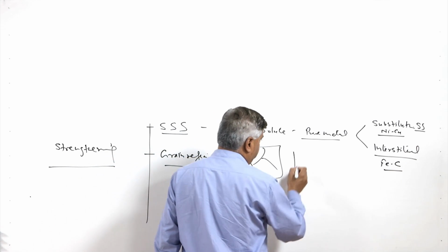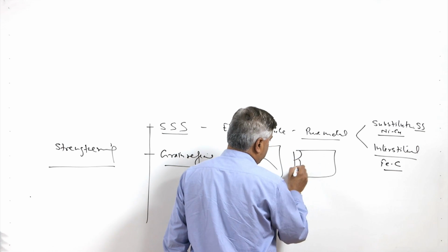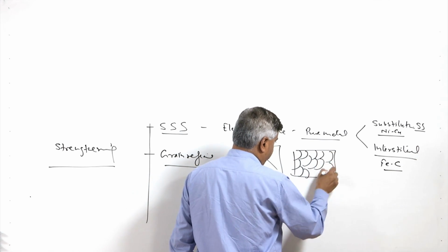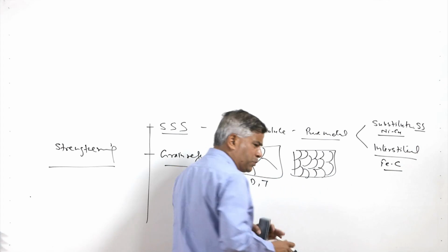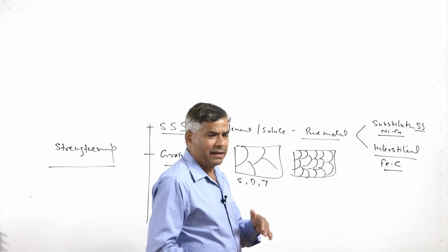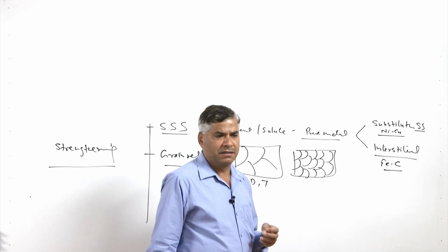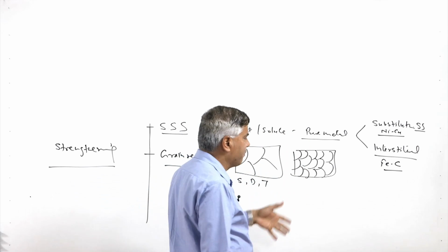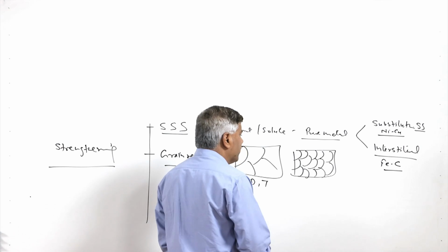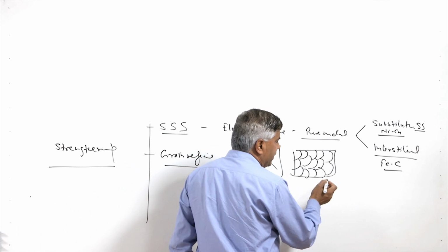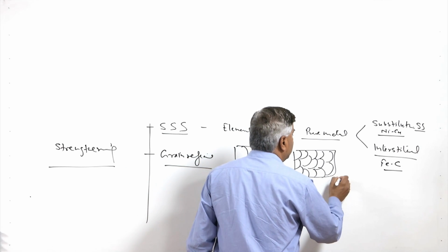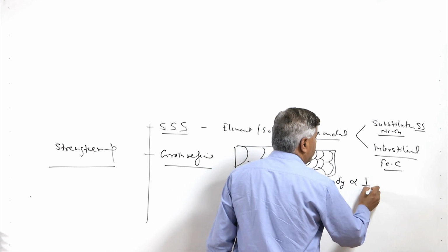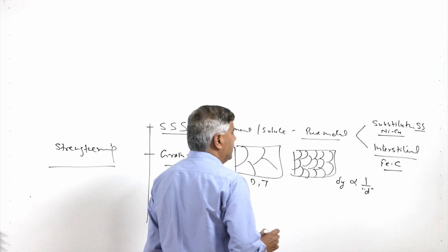So, if we refine the grain structure of the metal, meaning the phases present are made of finer size, using a variety of approaches like heterogeneous nucleation in casting, or heat treatment such as normalizing for refining the grains. Here the yield strength is found to be inversely proportional to the average grain diameter.